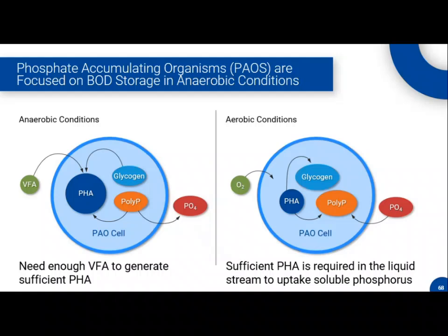That's what it is. So it's a great question on what glycol does. PAOs and heterotrophs might be impacted at a high enough glycol concentration, right? But what really controls the glycol limits at wastewater treatment facilities, and particularly Cruise, is the impact on nitrification. So the stuff we talked about yesterday, those AOB, and it kind of goes along the same lines, right? We're talking about energetics and favorability of growth and competition.